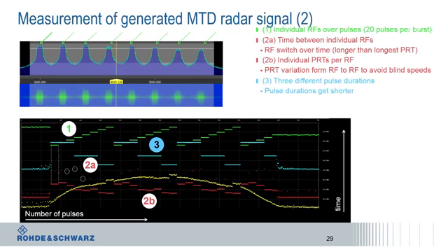In blue, the duration of the pulse is displayed. This radar is using 3 different pulse durations during its operation. And last but not least, the radar uses a rotating antenna. So in yellow, the received power levels per pulse are shown. So what you see here is the main beam of one circular antenna scan. We saw frequency plots, PRT or PRI plots, and pulse duration plots or amplitudes in one single window. This is possible as the y-axis can be changed so that all measurements can be shown in the same window, which gives you a good overview of the radar mode which is used.